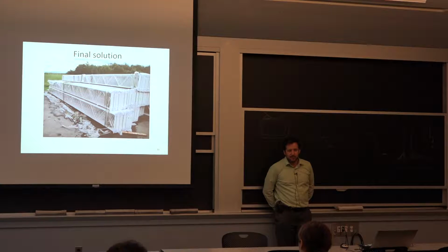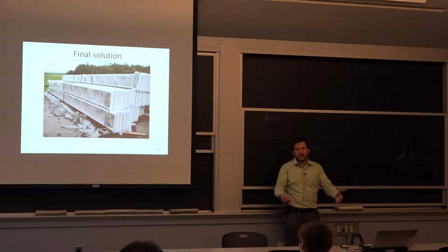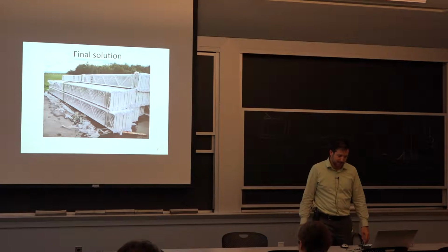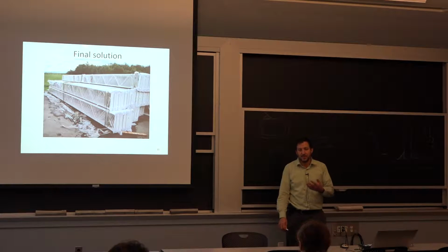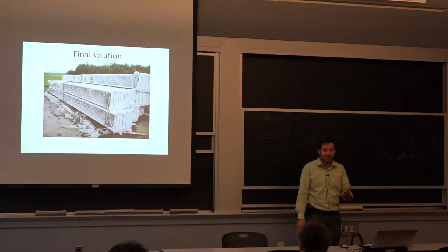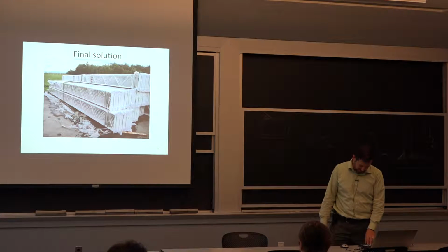They were very responsive, but they didn't like the idea of taking everything out. So they really wanted to repair in place, and we had to let them do it a little bit so they realized how long it was going to take. And then finally move on to get new joists. So we had a lot of shoring activities in the meantime to hold everything in place. It ties a little bit to, in terms of factor of safety, buildings do not have a huge factor of safety. So anytime something is not done exactly the way it's supposed to, then you can have a problem.